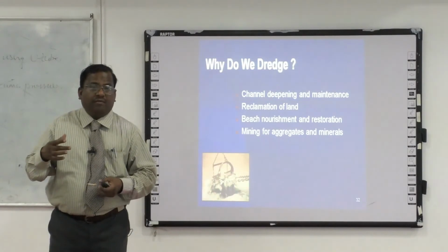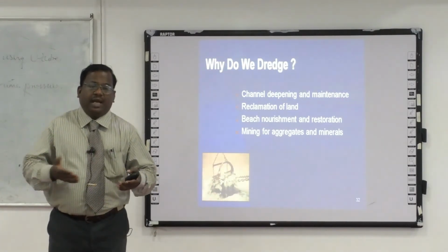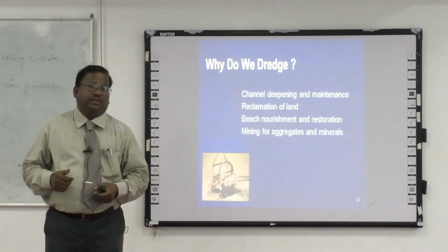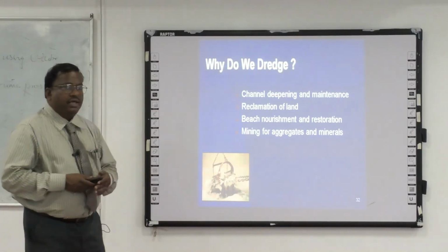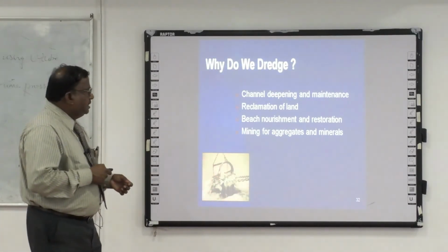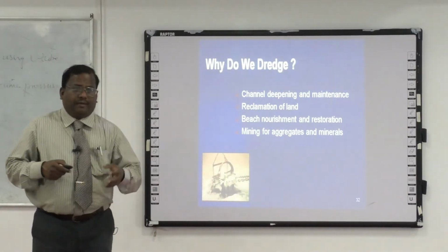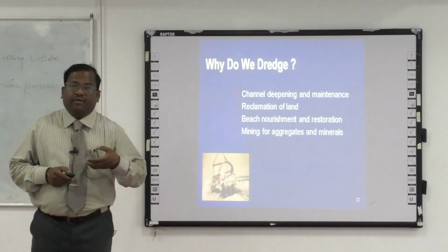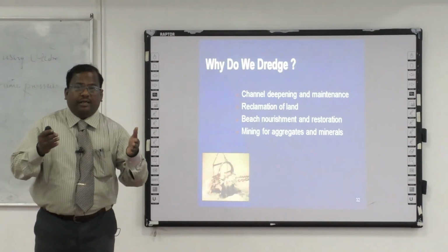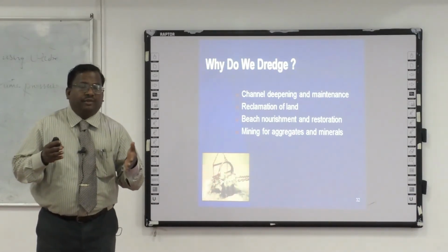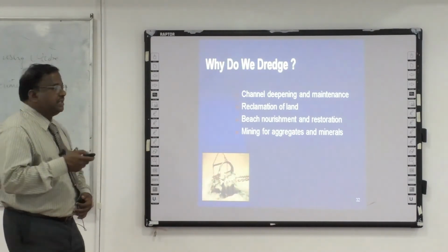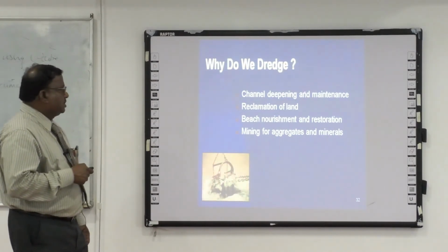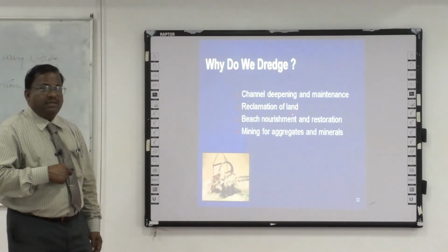The navigation channel will have several meters of width and depth, and a length of more than a kilometer from the harbor to the ocean. The navigation channel should have clear-cut dimensions so that it will not have any sediment accumulation, so that vessels have a convenient approach towards the ocean and the required draft can be maintained. The design of the navigation channel, especially the dredging aspect, is very important, and we need maintenance also. We have to maintain the sidewall depth and slope.